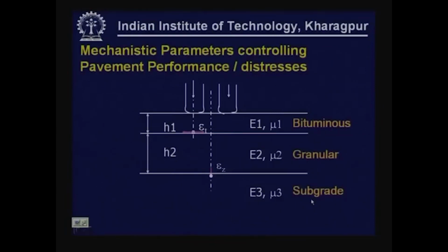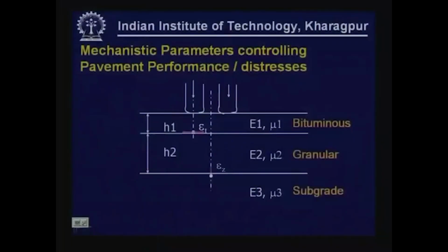We have discussed the general philosophy of pavement design in the very first class, lesson 4.1. We also discussed the analysis of flexible pavements, computation of stresses, strains, deflections in single layer systems and multi-layer systems. IRC 37 is a semi-mechanistic design approach in which the performance of pavements is explained in terms of the mechanistic behavior of different components of the pavement.